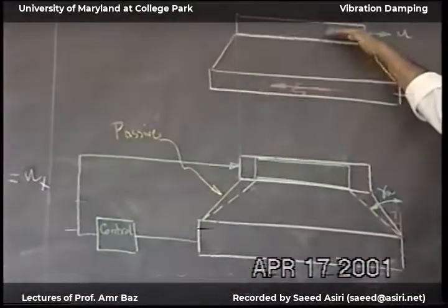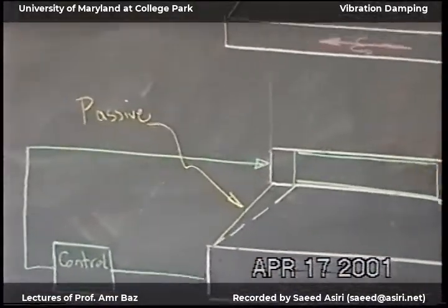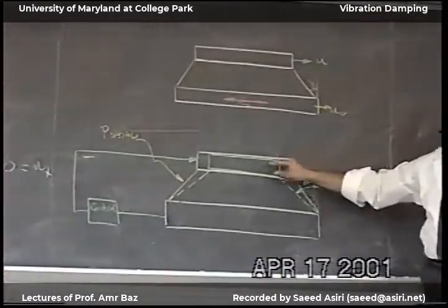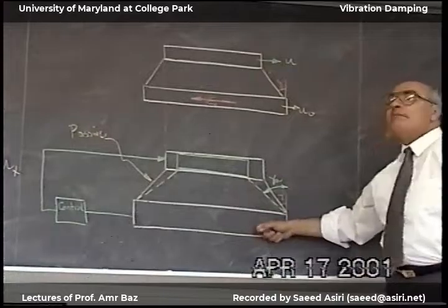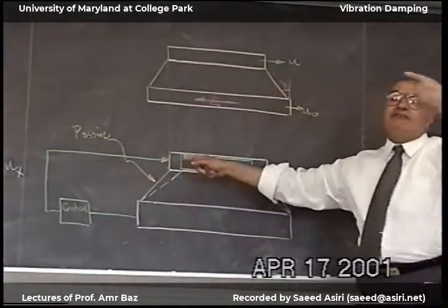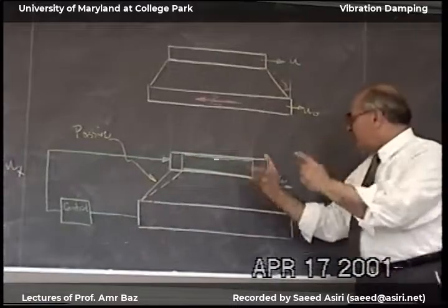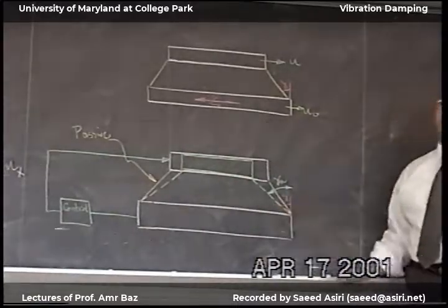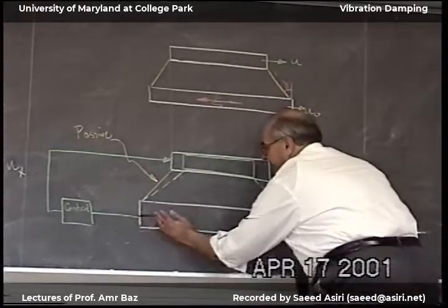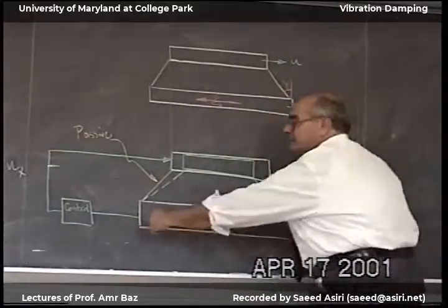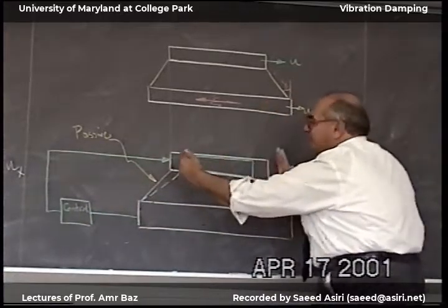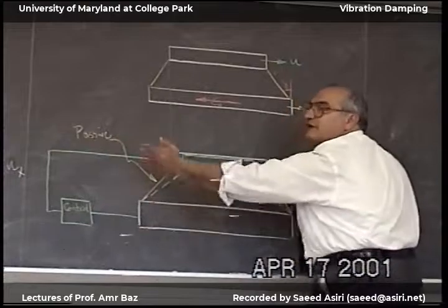And if instead of the constraining layer, which we said was a piece of aluminum, I make it a piece of piezoelectric material, then when I take the measurement of the expansion here and send it negative feedback, the top shrinks, and I increase the shear angle. If the reverse happens, if this shrinks, then I take the signal, feed it negatively back, so it will be positive, it'll expand, and have a much bigger shear angle also.